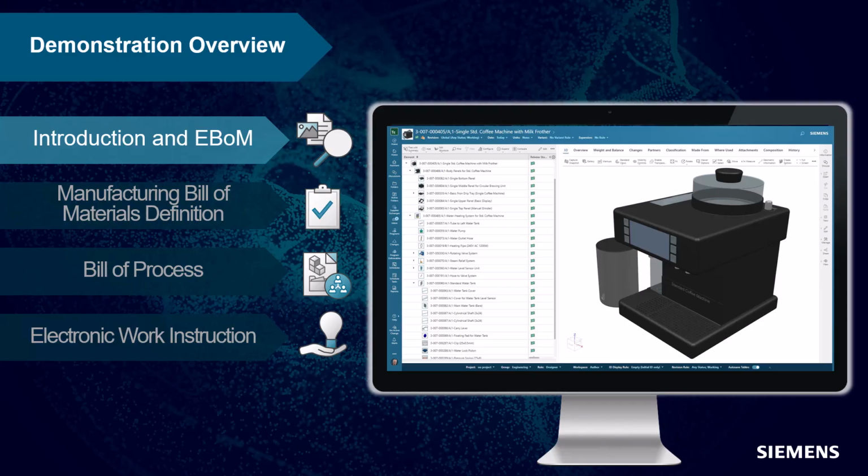We'll also see how design engineering have structured the EBOM and how this does not suit the way we would like to perform the assembly process, and hence the need for an MBOM. Finally, we will see where the components in the EBOM are used. This includes other EBOMs, MBOMs and bills of processes.